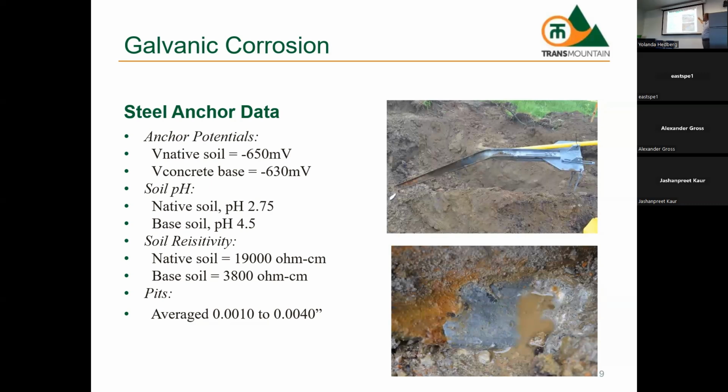This structure had a copper cable. I think it was like 2-aught, so about half an inch thick, or 3/4 of an inch thick copper cable. It was connected to the structure. So again, that's the galvanic couple between copper and galvanized steel. And the copper went to ground. It was wrapped around the concrete block that the support went into. Okay? Did it corrode? There was connection.